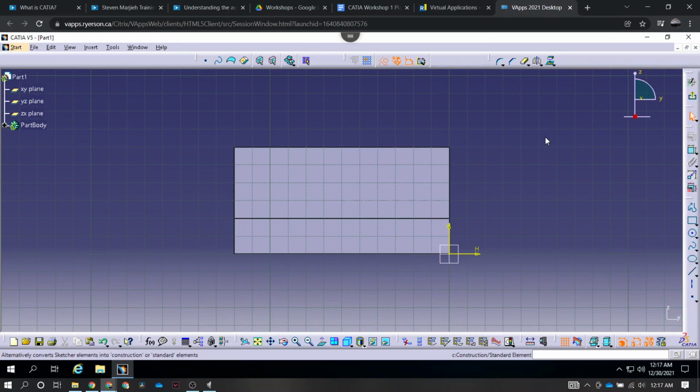What I like to do when there are a lot of complicated shapes is to create construction lines. Just click this, enable this, and all the lines that you draw will be dotted. Just like real life construction lines, if you draw portraits, for example, you do construction lines that you erase later on, or that you draw over. So they're not perfect, but they're straight, and we can just constrain them.